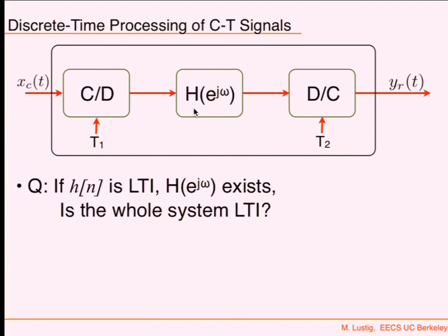Assuming no voice distortions, it's a pretty linear microphone, linear reconstruction, things like that. Is it LTI? It is, right? It is LTI. But would that always be LTI? No. So there's going to be some condition on which this system could be LTI. And the question is what is the condition that it should be LTI? Now ignore nonlinearity of distortions and things like that, because this is an ideal sampler, an ideal reconstruction.